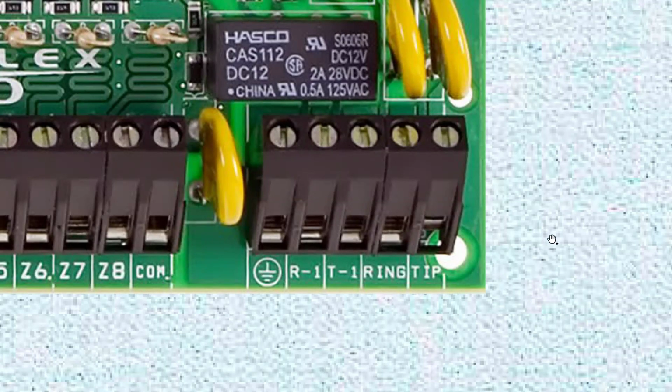So what happens? You get the phone line connected straight to this alarm, so the phone line has to pass through the security alarm. In the event of an alarm, this alarm system is going to steal the telephone line, disconnect the rest of the house, grab the line, hang up if it needs to reestablish the dial tone, pick it up again, dial the number that is programmed for the monitoring station, and communicate the messages.